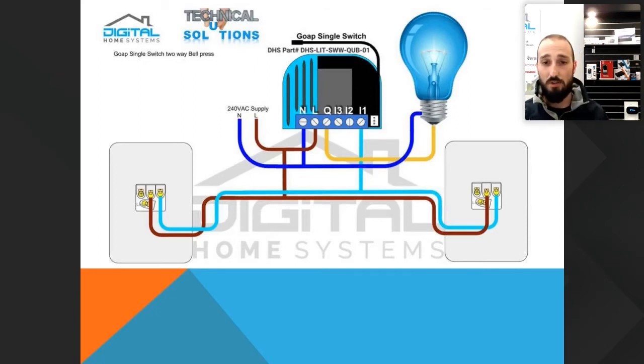If you aren't using a two-way circuit, it's really simple on this picture. You just don't include one of them and let all the cables still run to the same place. And then from there, you'll be okay. It's just important to make sure that you've got a complete circuit running through the device to the switch and then to the light bulb, as opposed to running directly to the switch from the physical switch on the wall to the light bulb and bypassing the device. You'd be surprised how often that happens.